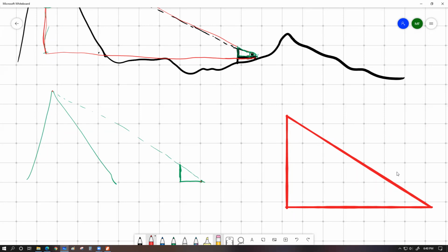No one remembers barometer, right? So only the height of the mercury. Thank you. Mercury column, sir. We measured the height of the mercury column. We did not measure the height of the whole atmosphere. So technically, we actually measured the pressure underneath the mercury column, and by law or by concept, by reason, we knew that this pressure under the mercury column is exactly equal to the pressure of the atmosphere. So we actually measured the pressure under the mercury column and equated that to the atmospheric pressure.